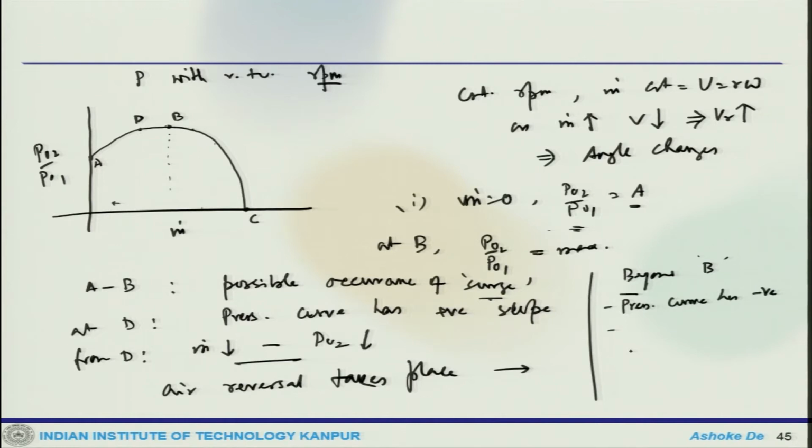So, air will then start to flow up the channel, and so does the other end, and then cause surging. That is why the number of diffuser vanes should be less than the number of impeller vanes. So, you can see this is another important criterion while designing these compressors, because if that happens, there is a possibility of occurrence of surge.